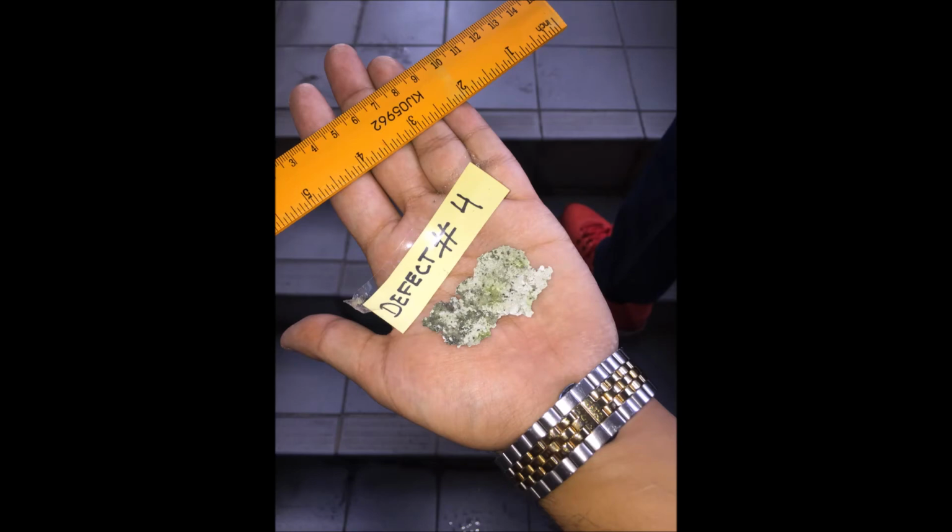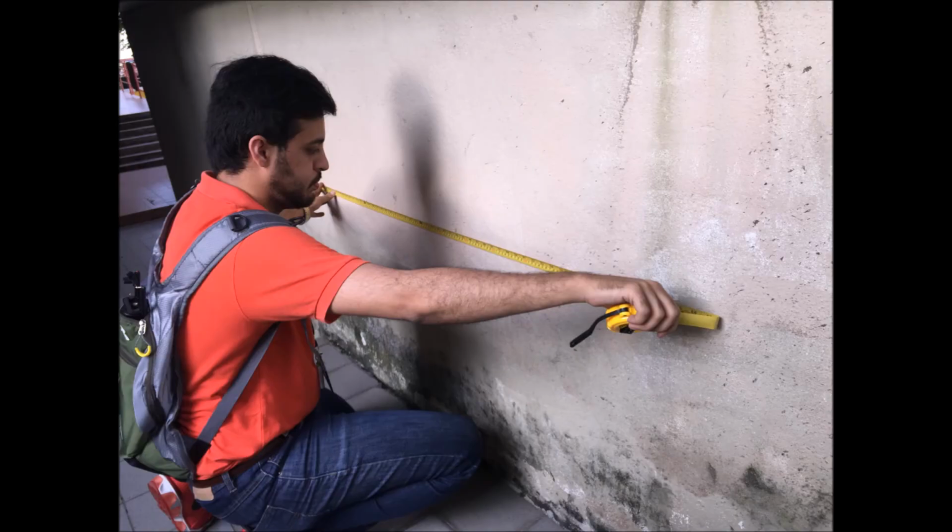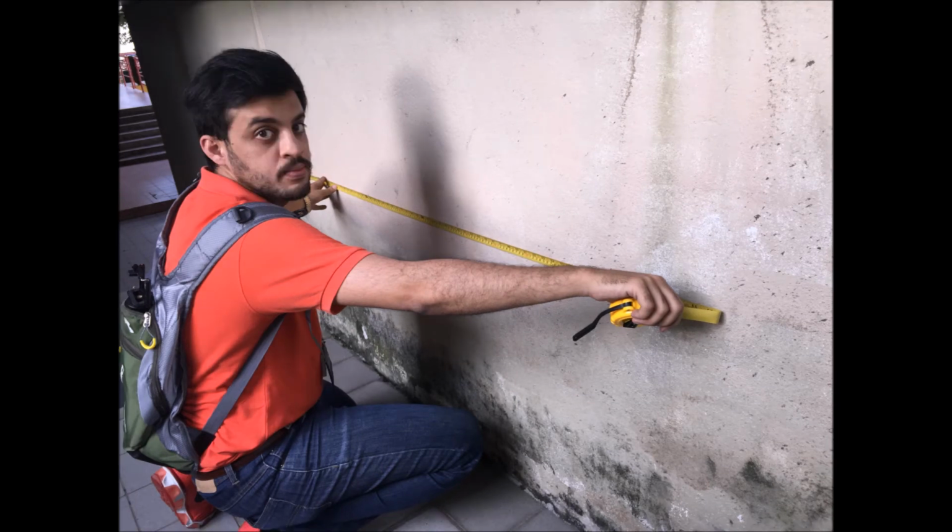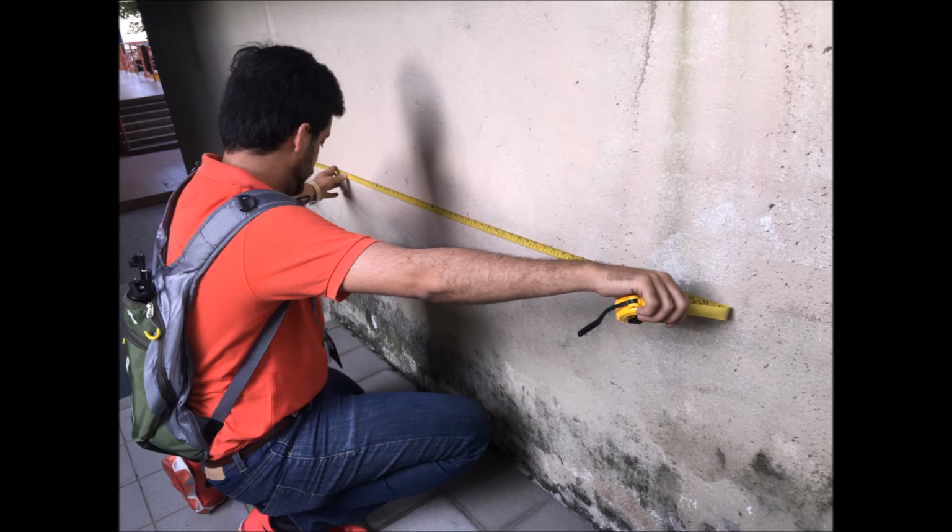Yes, for a cause there is a remedy. I came up to pour hydrogen peroxide on the wall and let it dry to remove the mold. Secondly, use bleach to make a solution of chlorine bleach and water to pour on the wall and let it dry to remove the mold. Lastly, use a spray of vinegar on the wall and let it dry for a couple of days to remove the mold.